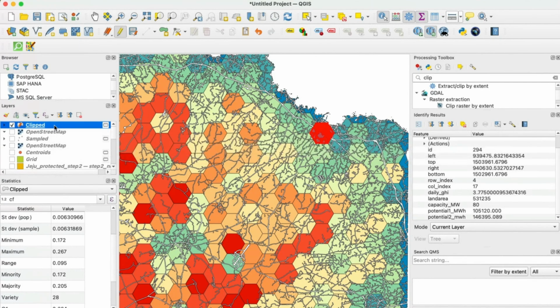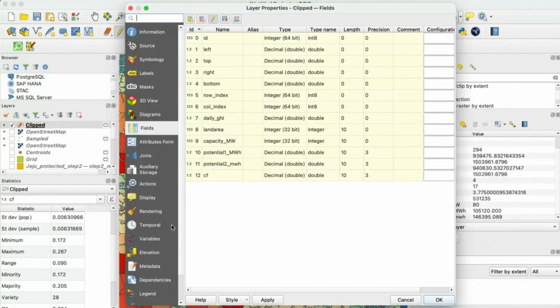Unless you are 100% sure that this value totally doesn't make sense, then you can create a new one. And then you can add some adjuster, like multiplying by 0.7, or you can reduce the energy efficiency of the system. That way you can adjust the mismatch between the theoretical output and the real, more technical output. Okay, and this is basically all about solar potential calculation.